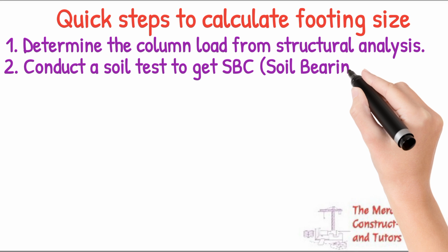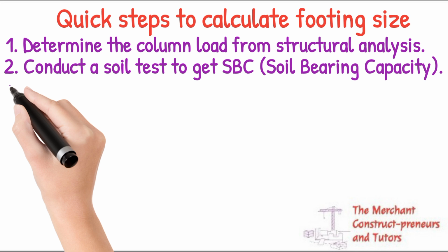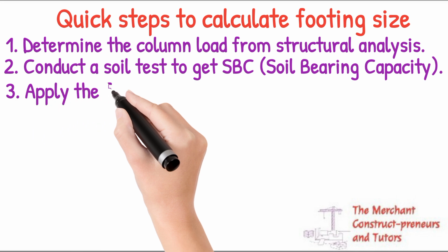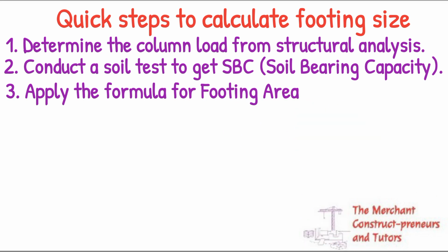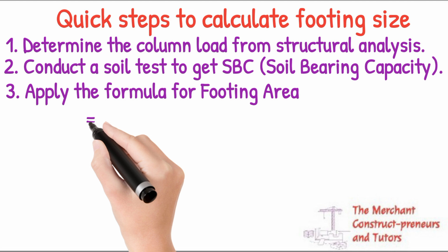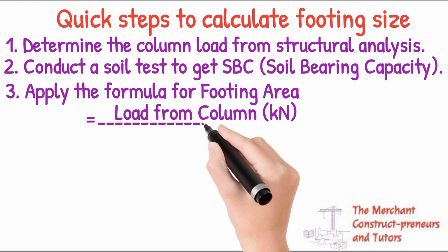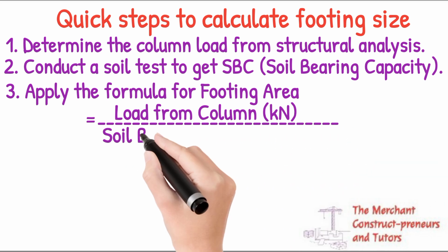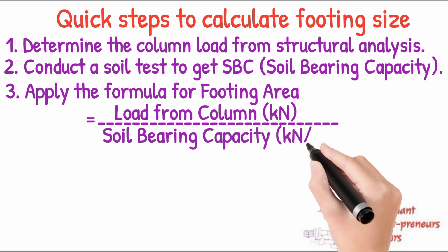A footing collects load from the building, which is sent down to the column, and the column sends it to the footing, and then the footing to the soil. So first you need to determine the column load coming on each footing from structural analysis. Second, conduct a soil test to get the safe bearing capacity of the soil.